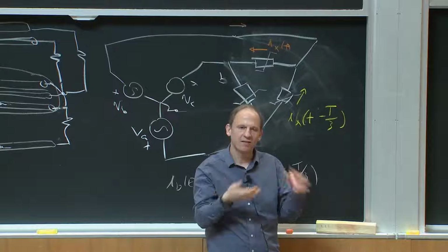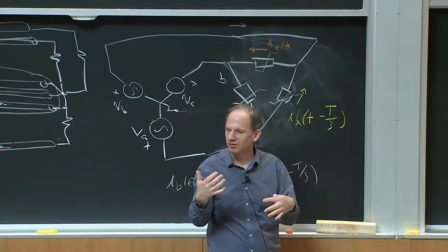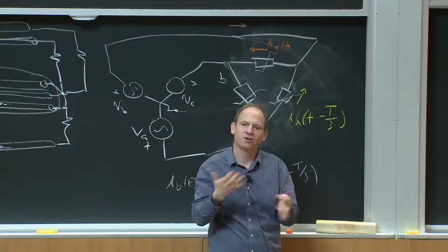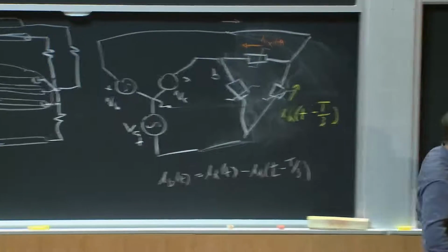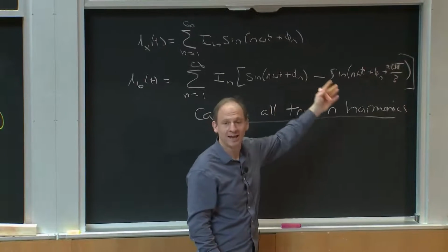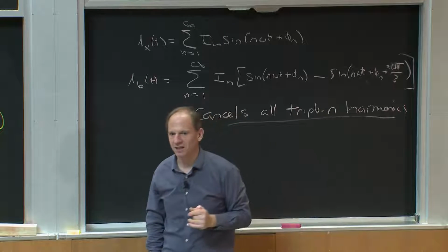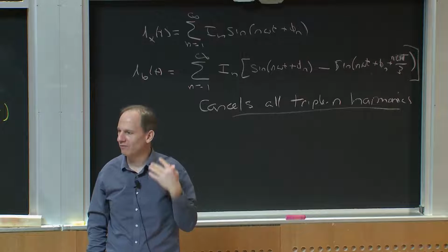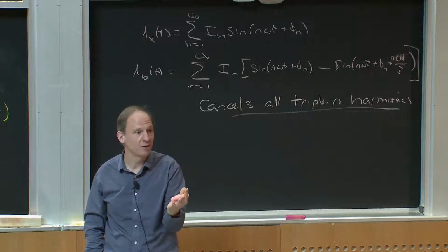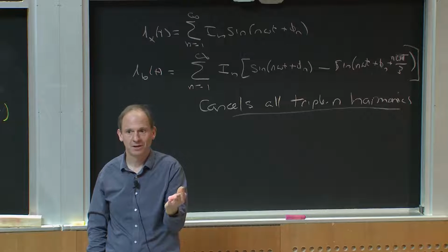So suddenly, even though I may have some rectifier that draws very funky current waveforms, I start to eliminate, or to be accurate, cancel out harmonic content I don't like, okay? And the 3-phase waveform set will give you that very beautifully, okay?